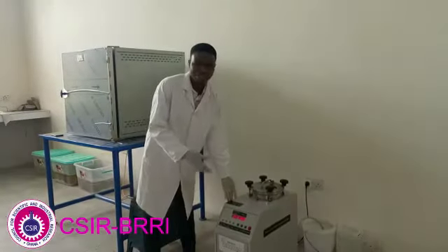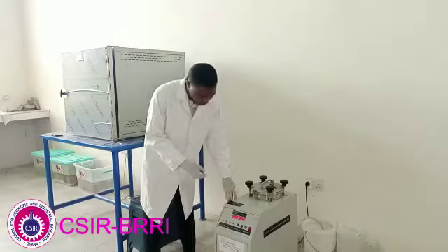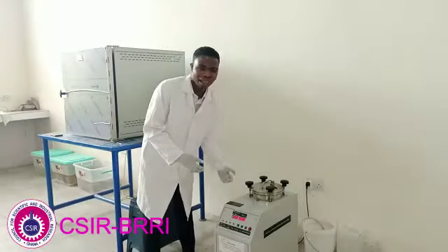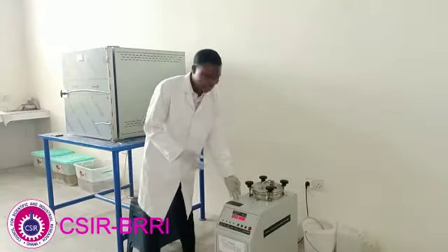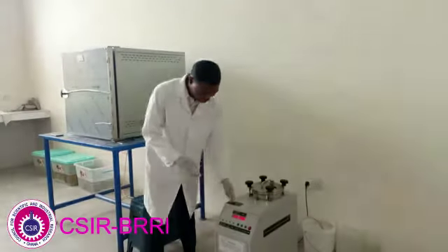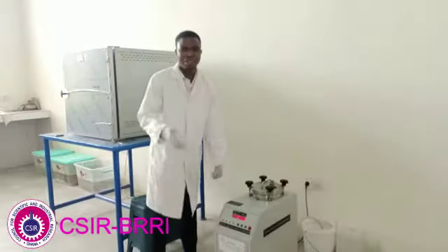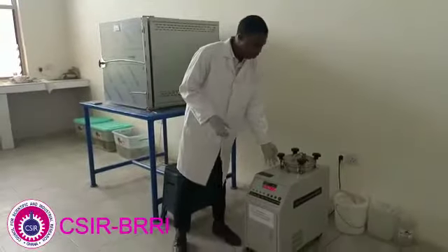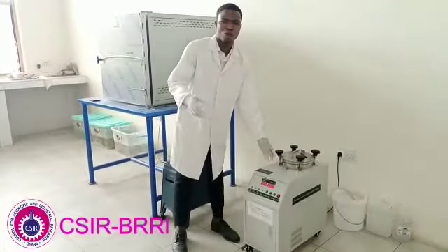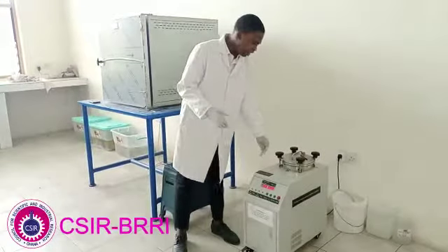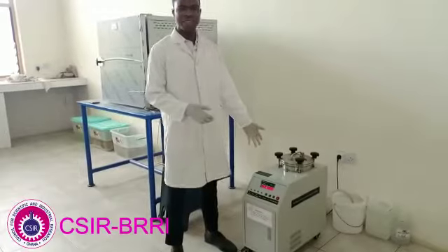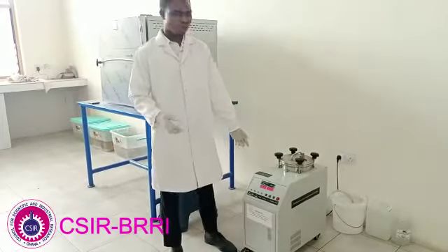Once the test starts, for the 3-hour period of the dry vacuum, it runs. There is an inlet which will allow water into the chamber, and then it will switch to the wet vacuum saturation. From then it will move to the static saturation, and it will stay there for 18 hours. So as I said earlier, the saturation takes place for 22 hours. Yesterday we started this, and the samples are ready for the test to be conducted.